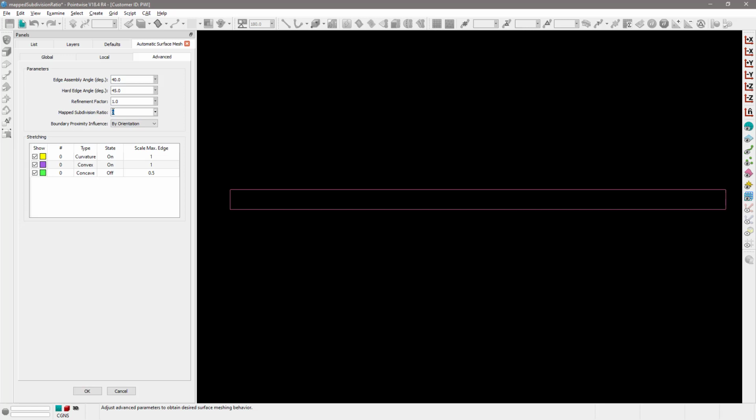And what that means is that the domain that is created using that set of 4 connectors is going to be an unstructured domain that is created starting from a structured domain. So there's going to be a special structure-unstructure mapping going on, and the final result is an unstructured domain that has a structure-like characteristic, which is, of course, very desirable for these kind of thin surfaces.